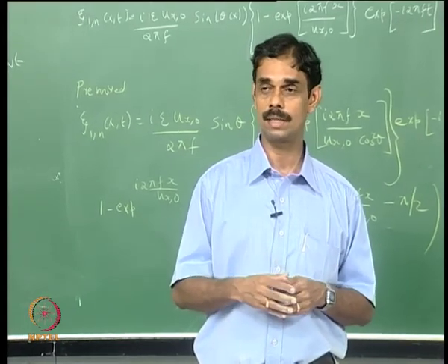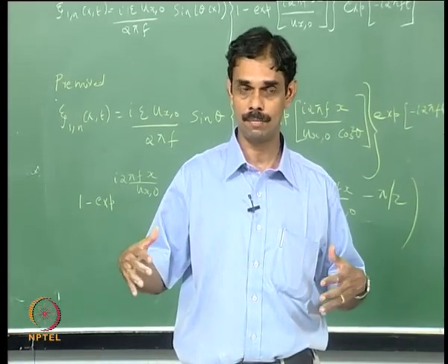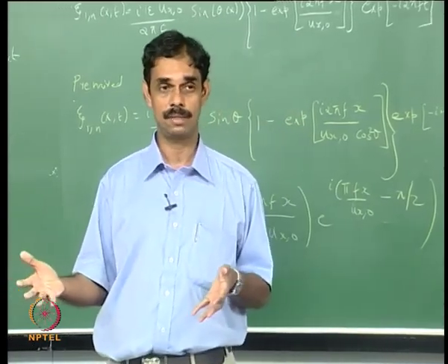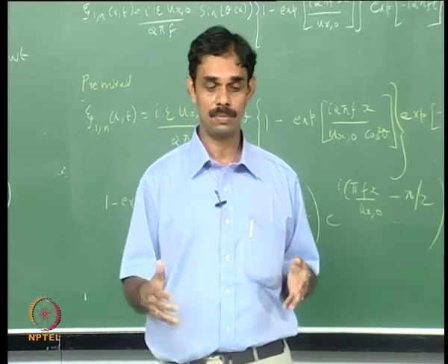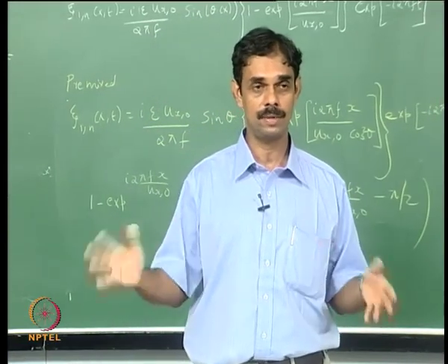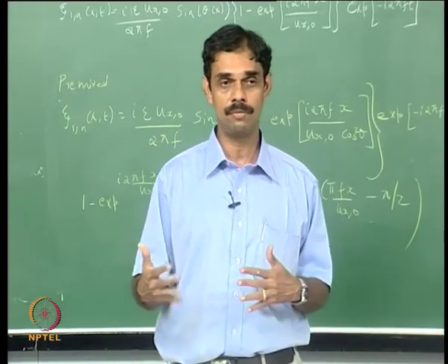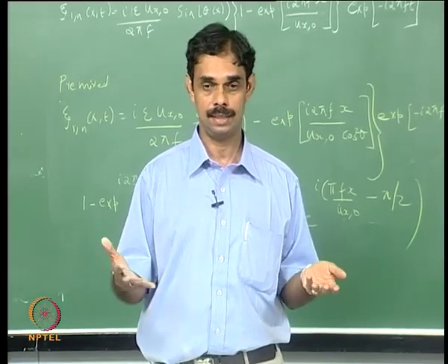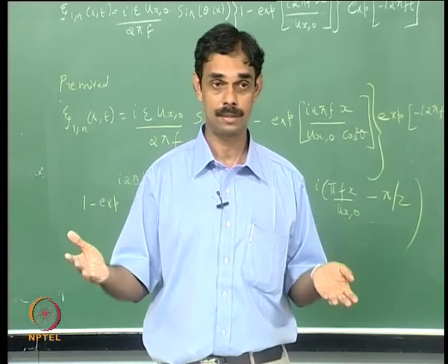But central to this calculation is the input to the model, which is the flame response, how the flame behaves in response to the fluctuations, and we have made models for several different systems. For example, just now we did diffusion flame, earlier we did a premixed flame, we have studied a lean premixed pre-vaporized flame.